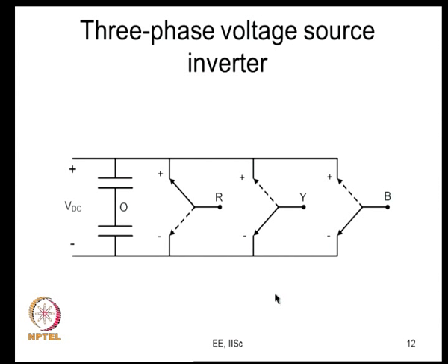What is the situation in a sinusoidal inverter? Here 3 phase voltage, you desire a sinusoidal voltage between VRY, again you desire VYB. So, again between VBR you desire sinusoidal voltages. Like you can look at average voltage VRY average. What do you mean by VRY average? Averaged over a subcycle, and similarly VYB is VYB averaged over a subcycle. We want these waveforms to be sinusoidal.